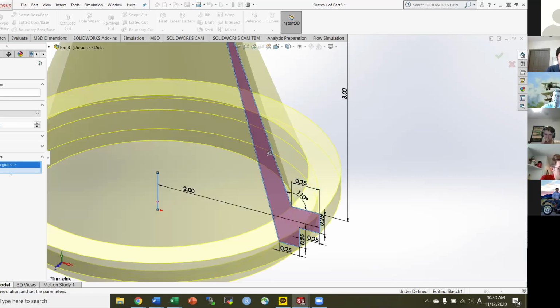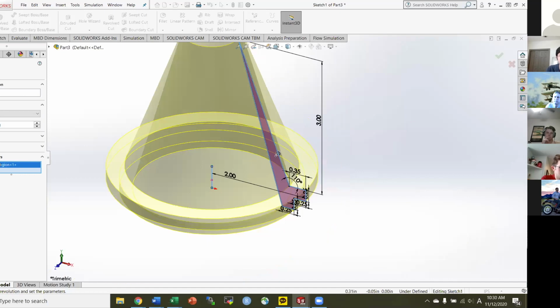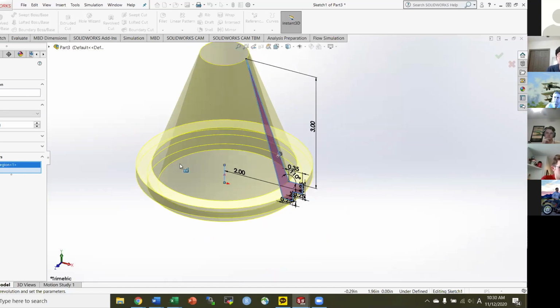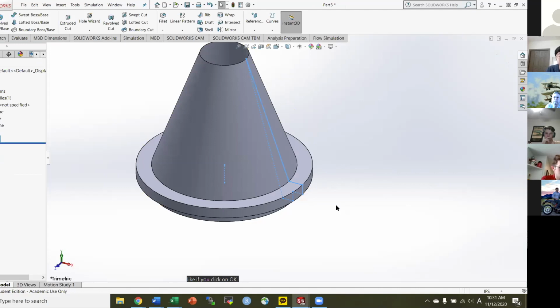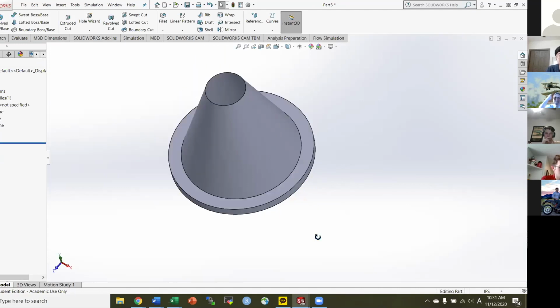okay, so the thin feature was selected, I guess by default, so you can remove that and then click on axis of revolution again, and then select the contour as this, and then it'll show up a preview. It'll give you a preview of what it's going to look like if you click on OK. This will be the cylinder shape that is similar to what I had.